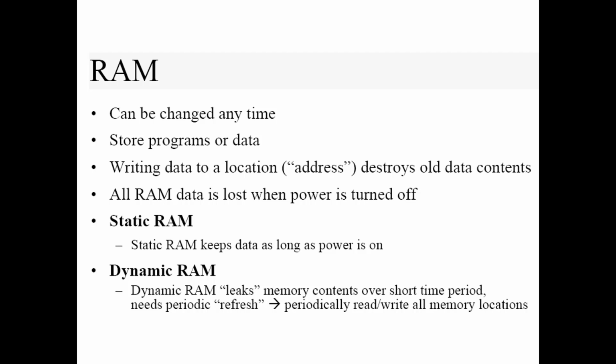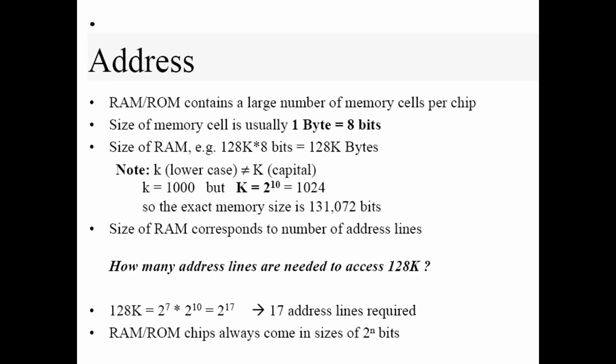As for the challenges and considerations, we have power consumption. SRAM consumes more power, which can be a concern in battery-operated devices. And in terms of cost, SRAM is more expensive than DRAM, so a balance between cost and performance is often necessary. Volatility: data loss on power-down requires careful management of data storage and retrieval. RAM is essential for the efficient operation of embedded systems, providing the necessary speed and flexibility for various applications.